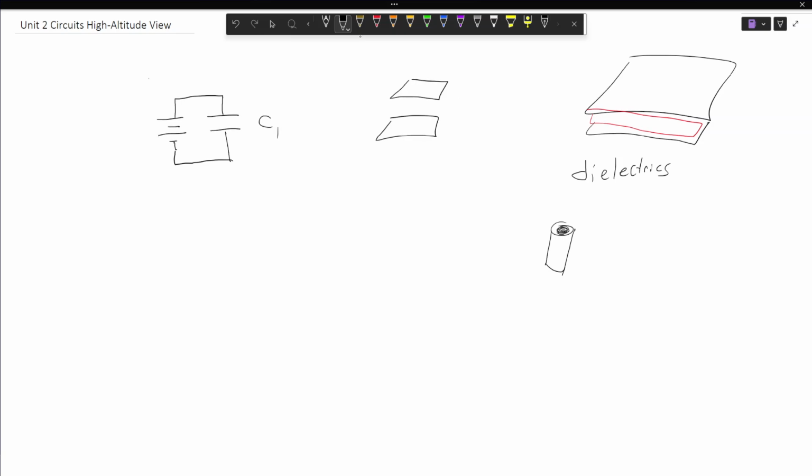And so this being the battery symbol, each cell of a battery looking like this, with the positive end being the longer one, the negative end being the shorter one. It's a pretty common convention that we'll see across a lot of different components in circuits, that if there's ever a reason for there to be a quote unquote positive or quote unquote negative end, we'd have those paired together. There's typically the short end of the circuit component. So based on the manufacturing here, the longer lead is going to be the positive end, and the shorter lead would be the negative end. And because you could just take some scissors and cut that, you're like, oh, we don't want that.